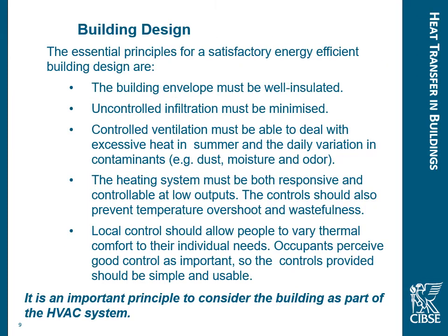So the building must be well insulated. Uncontrolled infiltration must be minimised. Heating system most responsive. And although I've put on this local control should allow people to vary their thermal comfort to their individual needs, in reality, we need to have a set point and people need to be able to stick to that set point and dress accordingly, really.